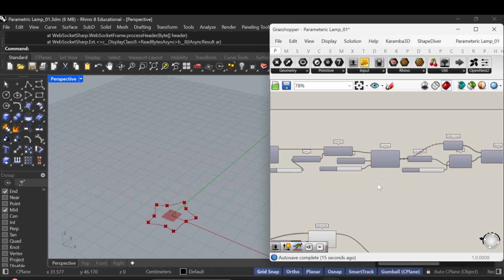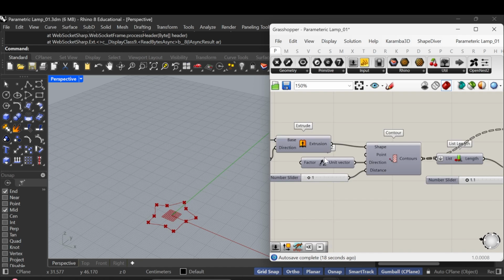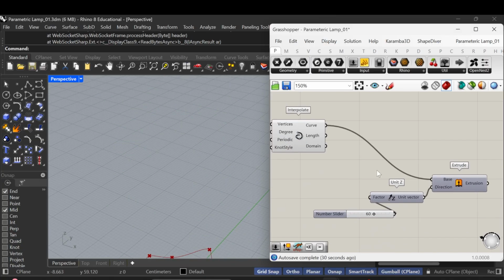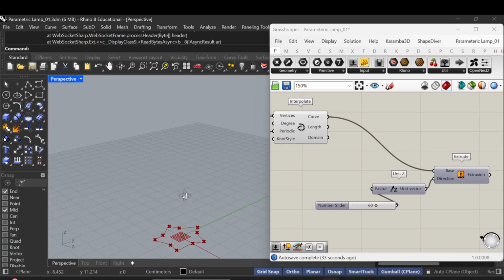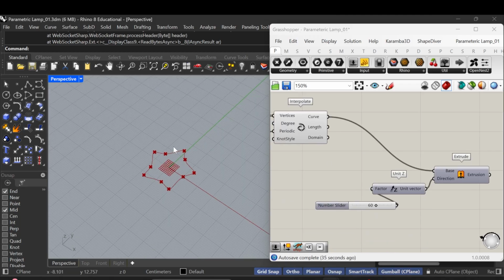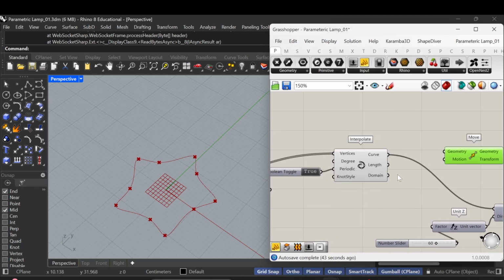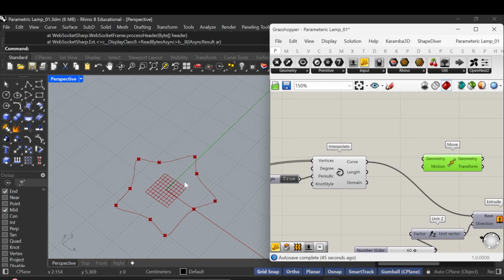Well, let me give you a note. In here I used a different method. I used that extrusion, then I used the contour to make a series of contours in here, but I don't want to use this system because in the workshop I used move, copy paste, move, copy paste and move, as many of these profiles as I needed.